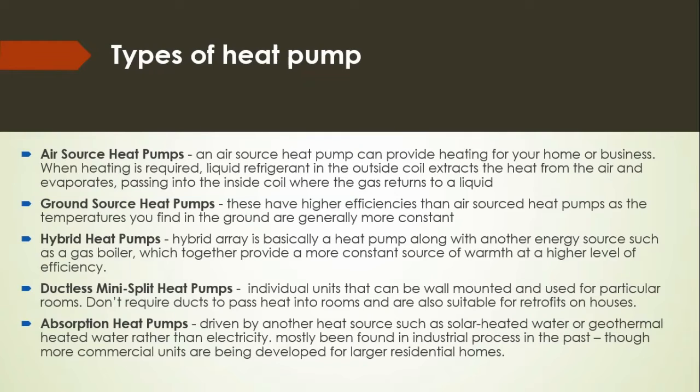For the ductless mini split, it is an individual unit that can be wall mounted and it is used for a particular room. This heat pump does not require ducts to pass heat into the room and is also suitable for retrofit on houses. And the last type of heat pump that we will present is the absorption heat pump.